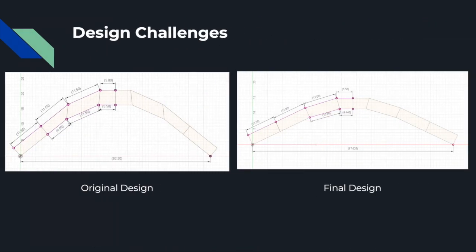Earlier in the video, most of the design challenges and constraints of our project have already been discussed. We will touch lightly on some of the more pressing issues again. Our greatest struggles were in attempting to design the bridge to be 5 pounds or less, and being cut appropriately to allow for both collapsibility within a cubic foot of space and ease of assembly across 5 feet. As a result, the original design we settled on was an arch bridge cut into 7 pieces that would have latches connecting each segment to the others and a tension cable to balance longitudinal forces along the span of the bridge.